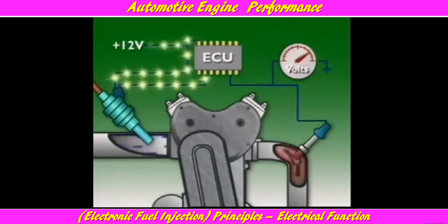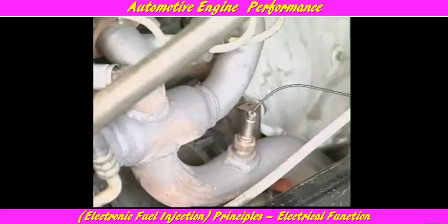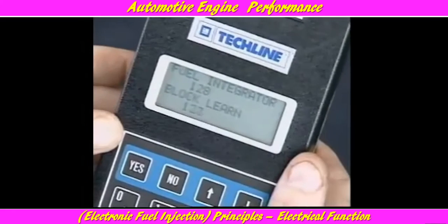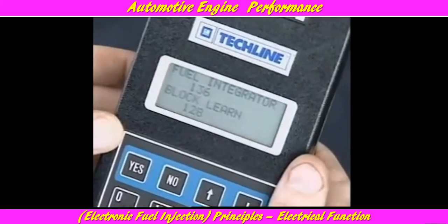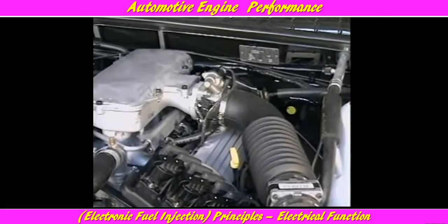The oxygen sensor in the exhaust manifold or in the engine pipe tells the ECU how much oxygen is in the exhaust gas. The ECU then varies injector opening time to achieve a correct mixture ratio. Feedback also lets fuel settings change as components age. This is called adaptive learning. The ECU memorizes its fuel settings for different operating conditions and stores them for future use.